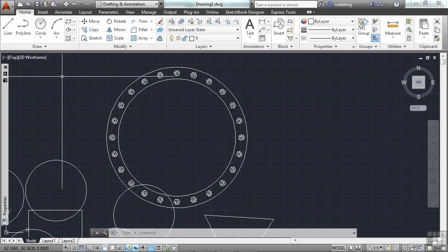There are some other palettes available, but their complexity goes way beyond the scope of this video, and we are going to look at some of them more closely later on. But suffice it to say, the palette is another format of a window that you can interact with inside AutoCAD. They can be rearranged in your drawing area, they can be docked or locked into position, or they can just float around and you can move them as you need to. They can hide themselves or they can stay open. You can right click, and remember, pick up on the right clicking here. You can right click on things, get more options to them. You can make the palettes as bars or just whichever you need.